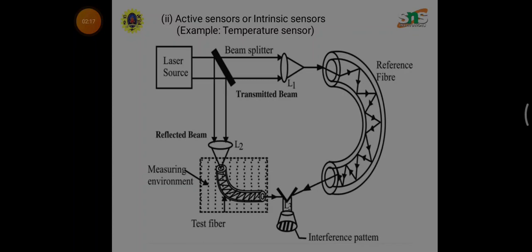Applications of fiber optic sensors: the optical fiber sensor has a wide range of applications in the measurement of various parameters such as temperature, pressure, flow rate, liquid level, current, etc. For example, the gyroscope is used to measure the number of rotations of the fiber coil. Fluoroptic temperature sensors are employed to measure temperature accurately. Pressure can be accurately measured using the photoelastic pressure sensor. Though there are many applications of optical fiber as a sensor, let us confine the discussion to one intrinsic sensor, the pressure sensor, and one extrinsic sensor, the displacement sensor.